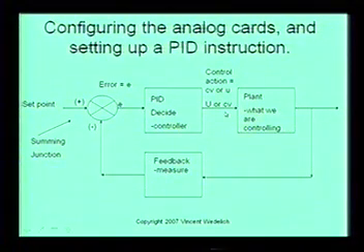And that might be 50-60% of the valve position. It might be 50% open or something like that, or 60% open. And then you're just sitting there modulating slightly, opening and closing. If there's any disruptions in the plant, such as a user all of a sudden just starts really using a lot of water and it starts dropping the tank level, then all of a sudden the measure will say, hey, wait a second, we're supposed to be at 75% tank level and we're down to 60%. So we have an error of 10.